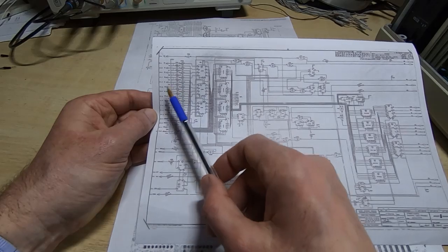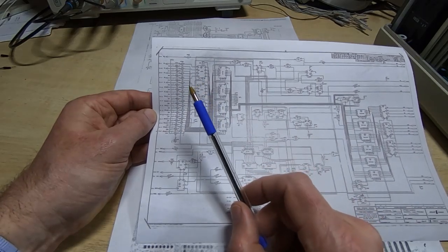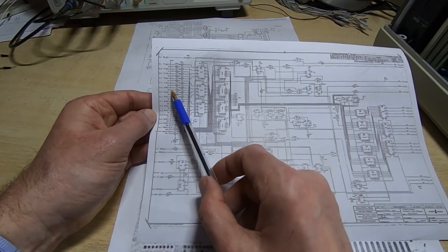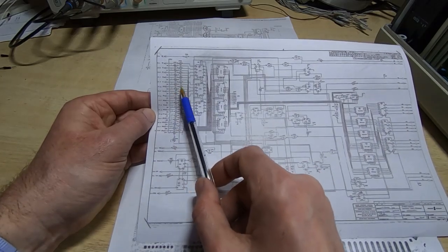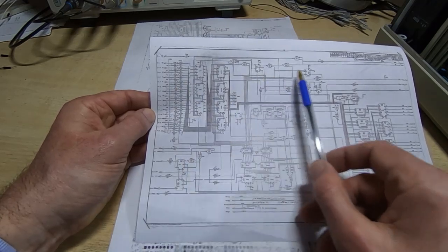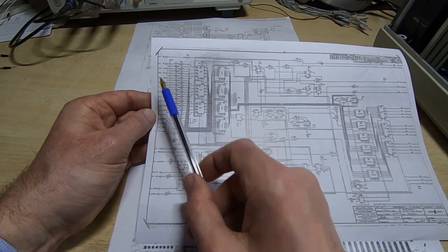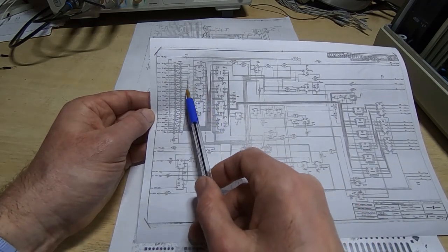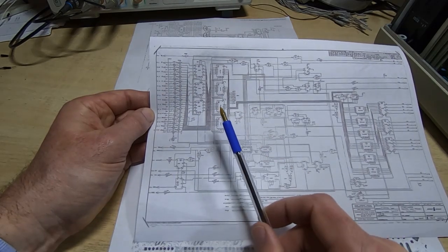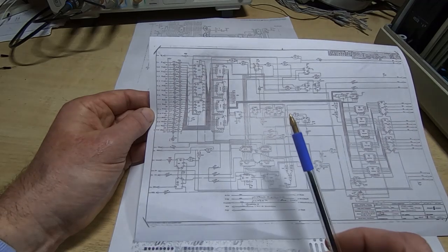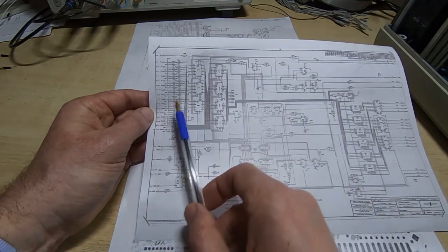This is connected inside of the main X and Y bus buffers, so it connects directly to the PPU hybrid module. This is a bidirectional buffer, and it allows us to get data into our video system. Usually it comes from the system RAM, and it also allows us to feed out a value to the PPU, and that is the address of the next data that we require.